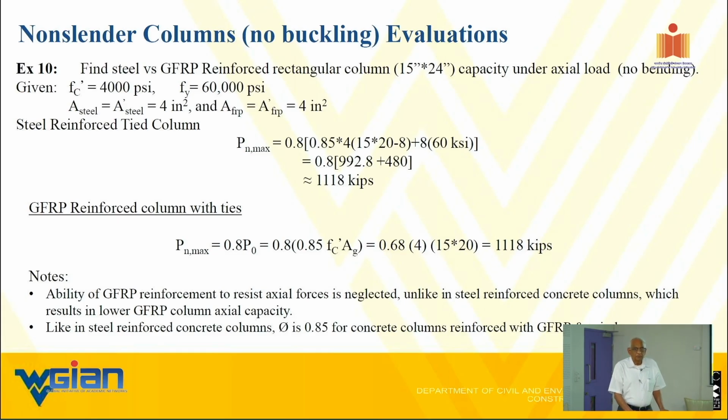How do you separate the slender column from a non-slender column? That's one. If it is a slender column, what is the controlling factor, which is pi square EI over L square, Euler's equation for slender column. The third thing you need to know is boundary conditions of the column. The L effective in pi square EI over L square, that L is effective length.